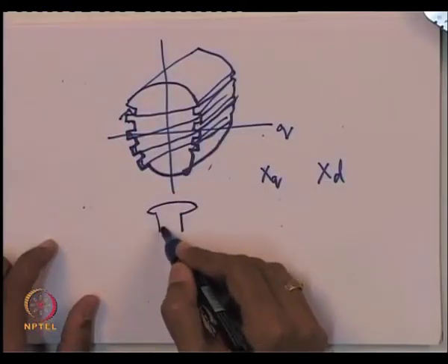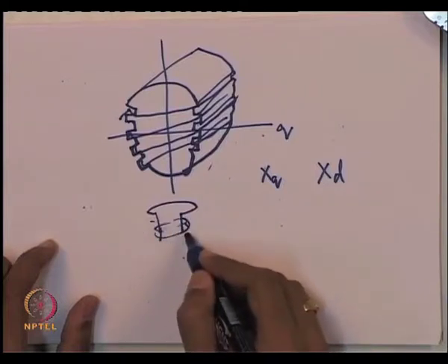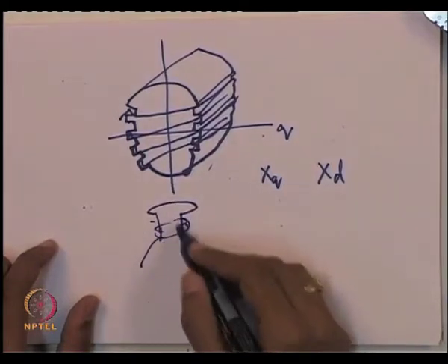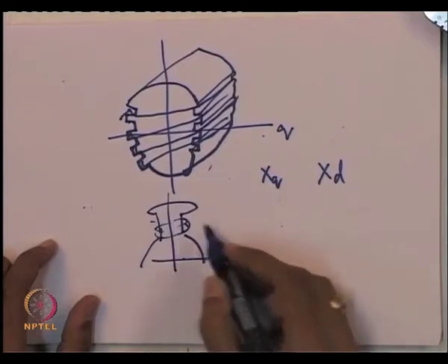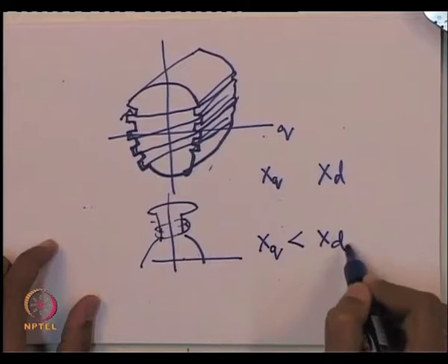Of course, in a hydro generator, there is actually a proper salient pole, and field windings are concentrated and wound on the pole. So, you will find that x q will be very distinctly less than x d.